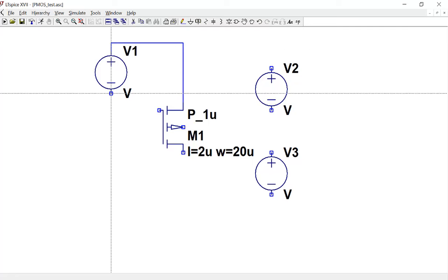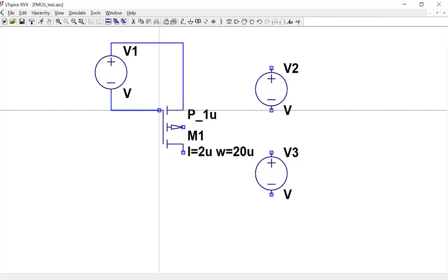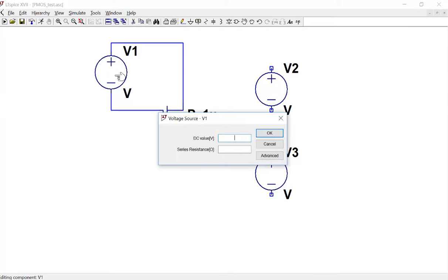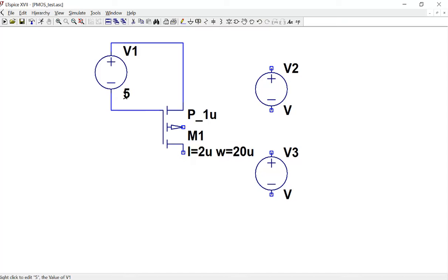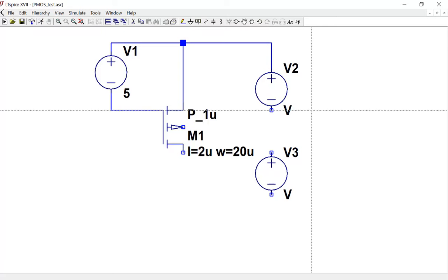The voltage source is gonna do whatever you ask it to do. Keep in mind, if you want to drop the voltage from source to gate, it doesn't matter because we are going to do a DC sweep. Let's just put 5 volts here. It's way larger than 0.9 volts, which is the threshold voltage, right? And then I want to give a potential from S to D in order to drive the holes from top to bottom, right?